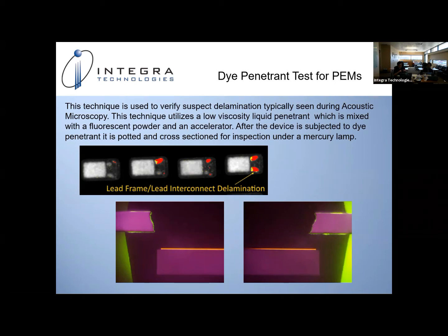It doesn't have the level of depth that there is. I would say, in the majority of the cases, in some cases you will see it, but the acoustic microscopy type voids, a delamination or the like, no, you cannot see that in X-ray. If it is a gross crack or something like that, yes, you will be able to see it in X-ray. Yeah, if it's gross enough for PEMs, you would see it in X-ray, but it has to be gross.